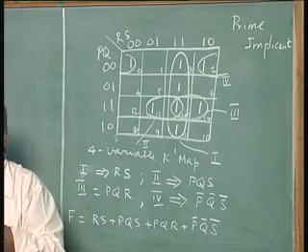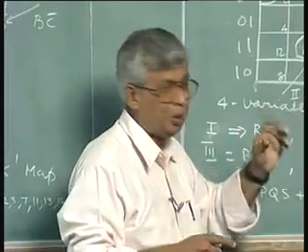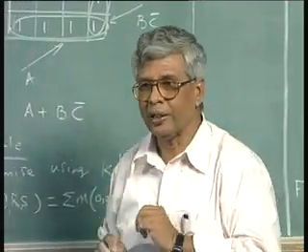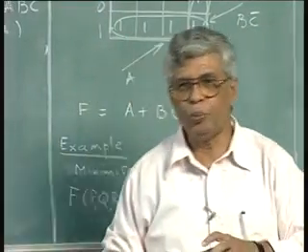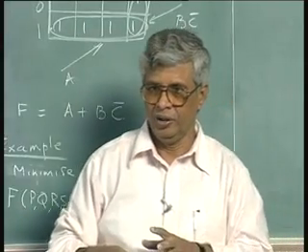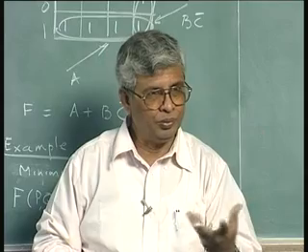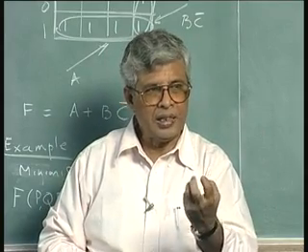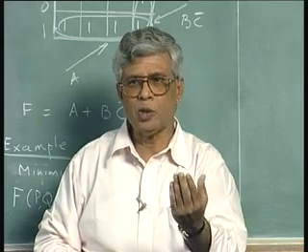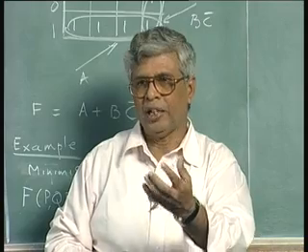I will not do it because I am covering a larger group of ones, 4 ones. So, there is no need to do this. Suppose I did it, it is called an implicant, it is not a prime implicant. A prime implicant is a group of ones, the largest possible group of ones in that particular context. For that group you cannot find a larger group. An implicant gets submerged into a prime implicant. A prime implicant is the largest possible group of ones that you can find for a given group,